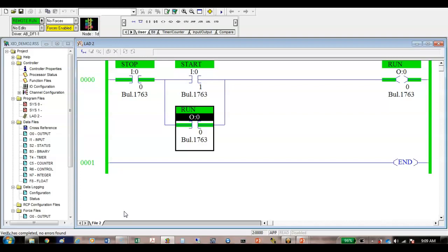When it's closed, right? So on your diagram, the next lab that you're going to do uses a normally closed limit switch. Which contact are you going to use for that normally closed limit switch? You're going to use an examine if closed instruction. That makes sense. But somebody here is going to make that mistake, especially if they've had motor controls.